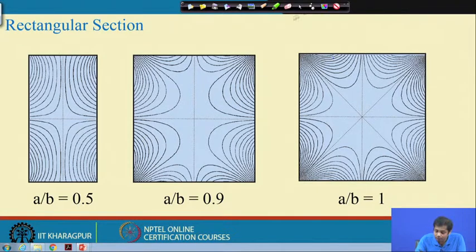Now, you can have a cross section like this as well, like a channel section, and this is subjected to torsion. In the same way you can apply it to get the distribution of this warping W, or to get the distribution of stresses on the area.